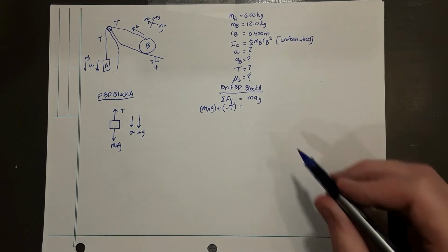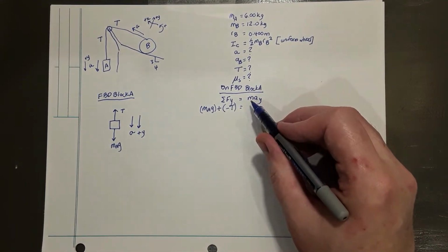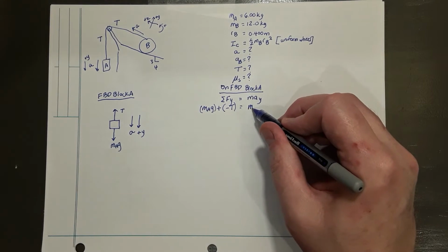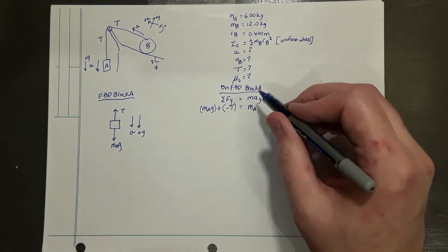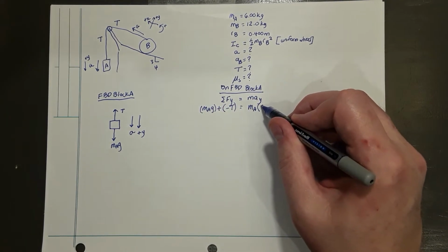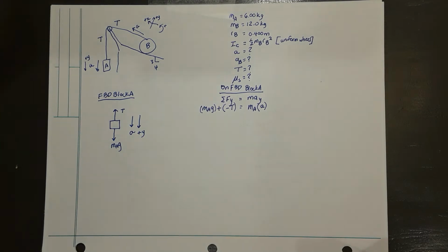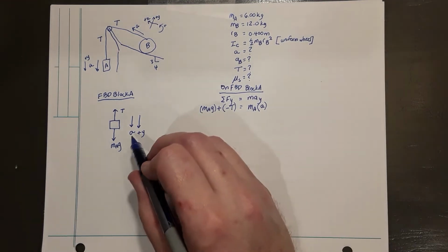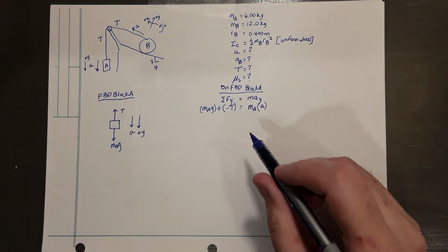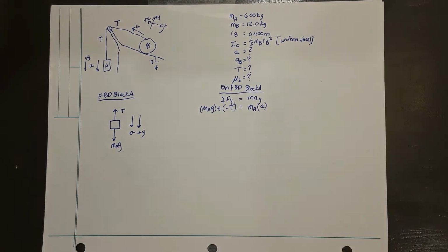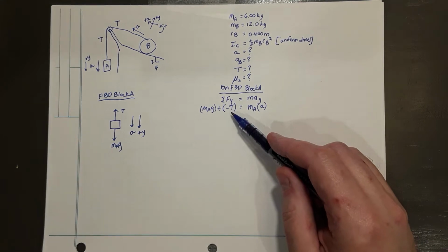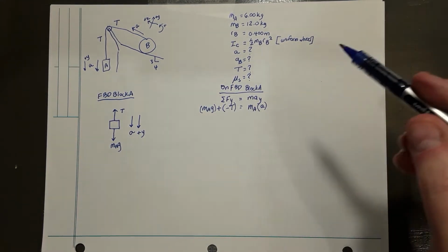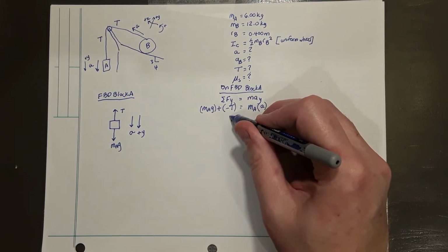On the right-hand side, we put in the linear inertia, the mass of the object in this diagram, which happens to be specifically mass A. And the acceleration in the y direction happens to be unknown, but it is a positive quantity, unknown acceleration, positive a. Positive because it points in the same direction as positive. There are two unknowns in this expression, tension and acceleration. If I solve for acceleration, I end up dividing by mass. If I solve for tension, I don't have to do any division. So it's actually easier to solve this equation for tension.